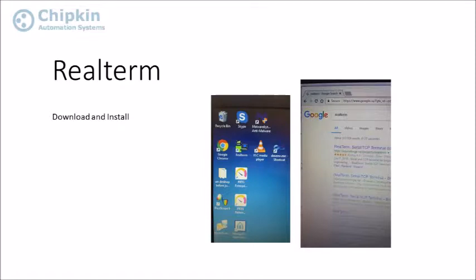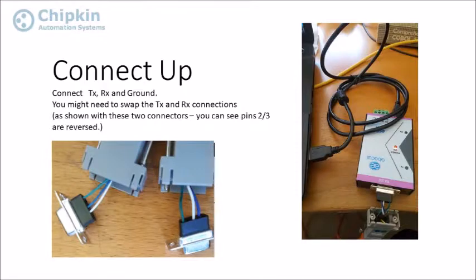Now it's time to connect to the device that's transmitting data. Let me tell you what I mean by the device transmitting data. We're listening to a 232 port. We're not generating data. We've got to get the data from the device. So if that device is a server device, a slave, you're not going to get anything out of it because it's waiting for you to send it a message before it responds. For the purposes of this movie, I am assuming that the device we're going to connect to is transmitting data to us, and then we're going to capture that data. In other words, it's a master if you're talking Modbus or something like that.